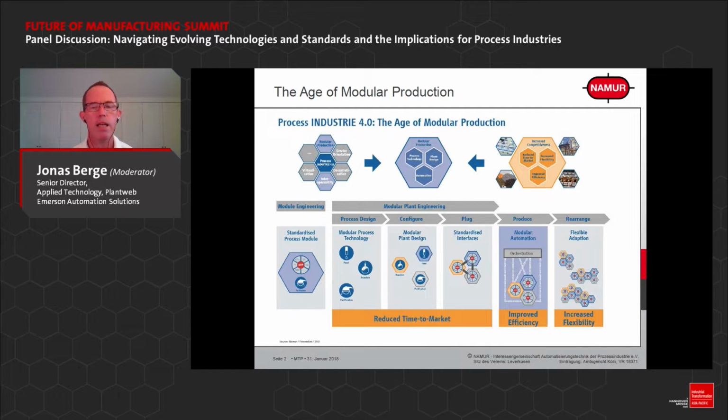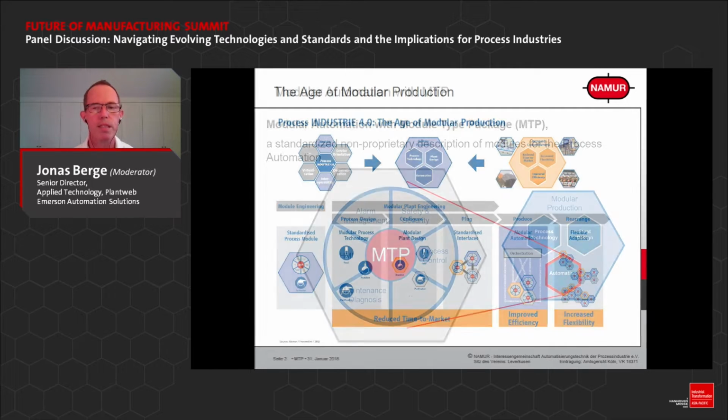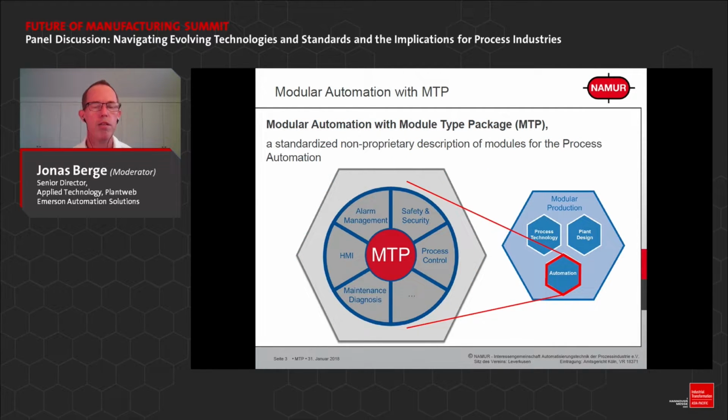But with MTP, we make it a lot easier through OPC UA to integrate all of the data in the package unit PLC into the main DCS. That includes all of the alarm management, control strategy, HMI graphics, all of these pieces. They now get full access to the data in the package unit PLC.